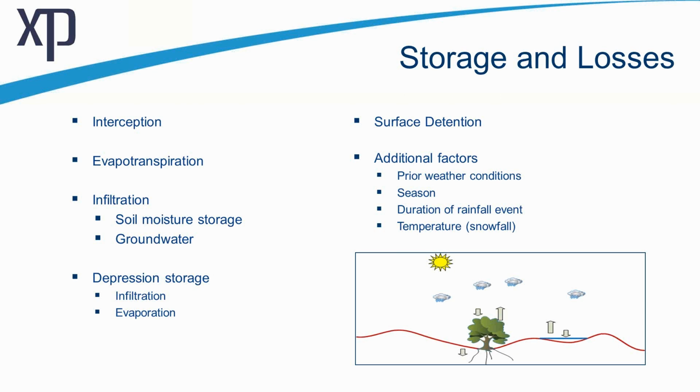Again, we have these long duration runoff events that exist beyond the Great Dividing Range here in Australia, where a lot of places and towns along the way, along the Murray-Darling system, they'll typically have what's called sunny day floods. The rainfall may have occurred 2 weeks prior to the event, and they can be having a great day when the flood turns up. So these losses are definitely a continuing element relative to our rainfall.